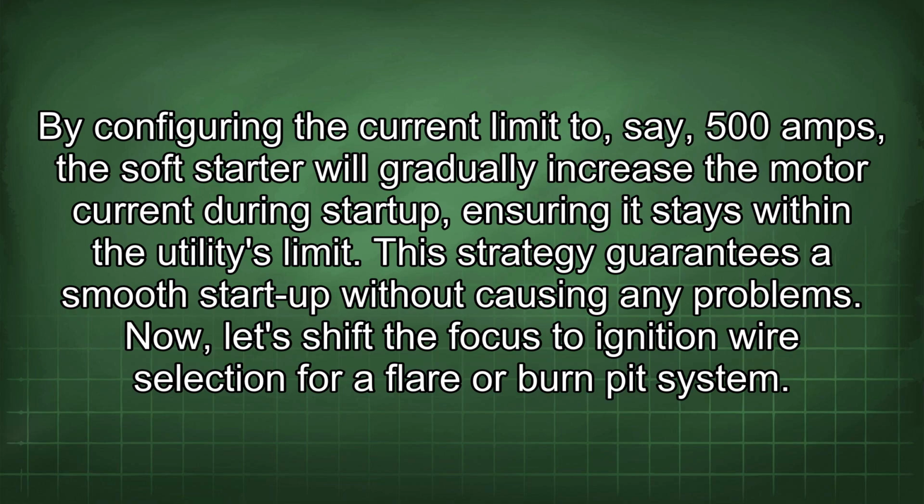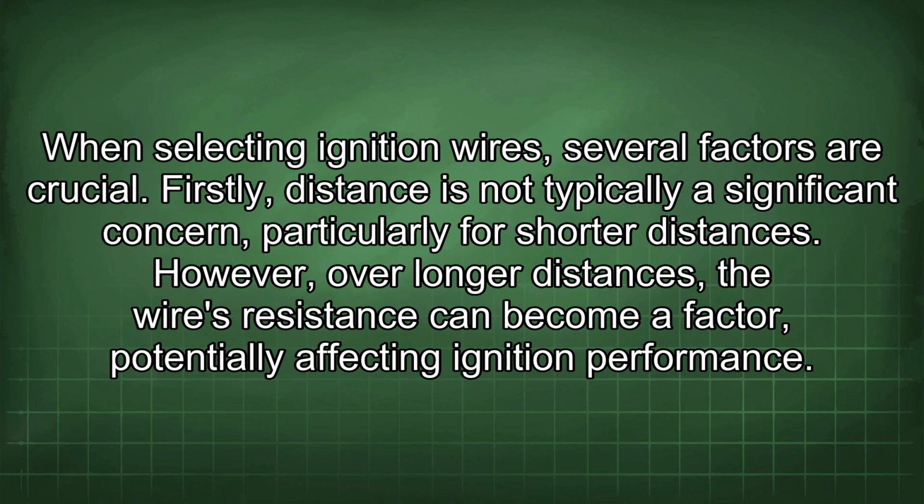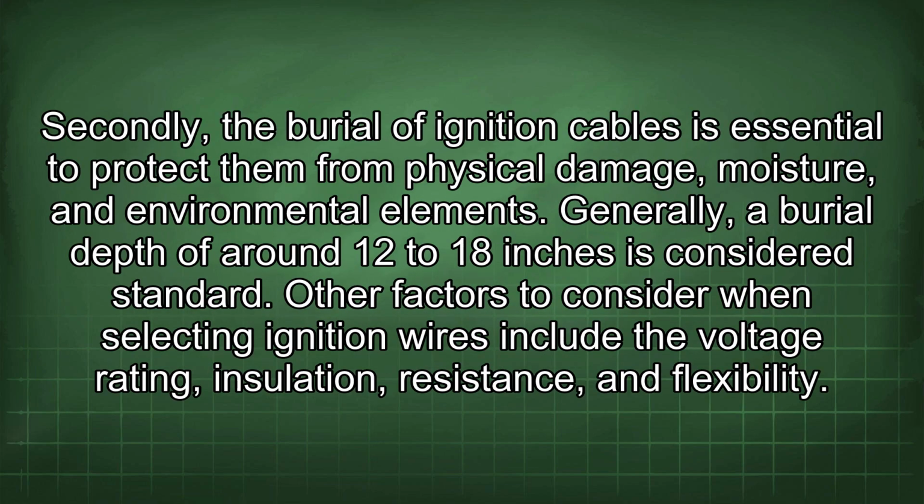Now let's shift the focus to ignition wire selection for a flare or burn pit system. When selecting ignition wires, several factors are crucial. Firstly, distance is not typically a significant concern, particularly for shorter distances. However, over longer distances, the wire's resistance can become a factor, potentially affecting ignition performance. Secondly, the burial of ignition cables is essential to protect them from physical damage, moisture, and environmental elements. Generally, a burial depth of around 12 to 18 inches is considered standard.